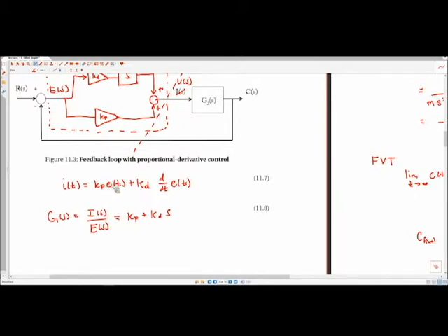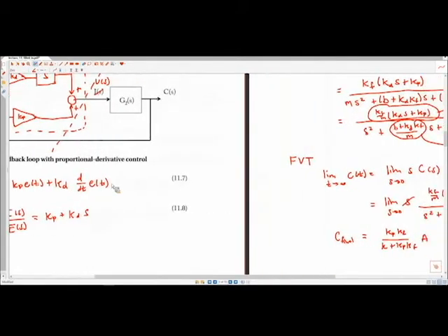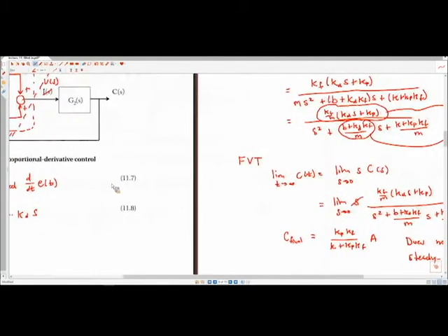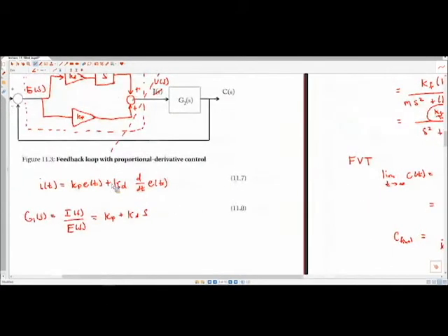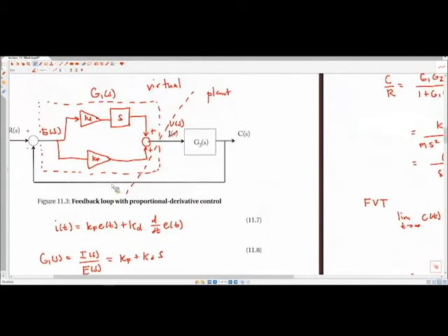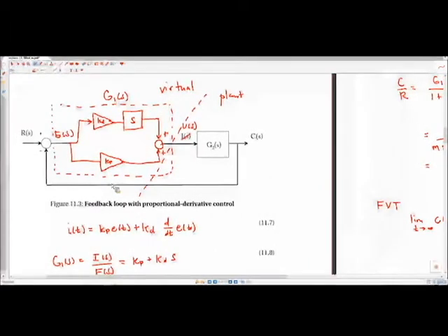And also, for those of you who were here the Friday before spring break, we talked a lot about the relationships between steady state response and system type. And so you'll see that we have not increased the system type at all here. If we look at the system type of G1, G2, we have not added a pole to the system, we've only added a 0. So the system type is the number of poles at the origin of the system. So we haven't influenced it at all, so we would not expect it to influence steady state error at all.